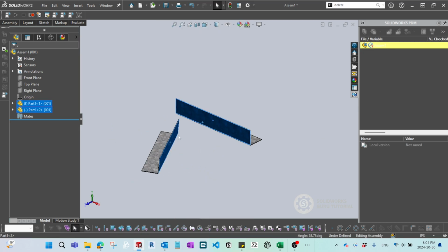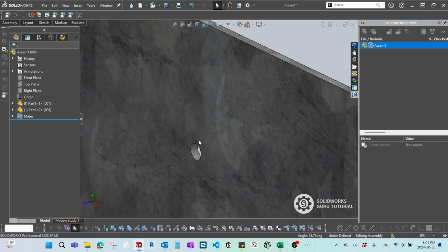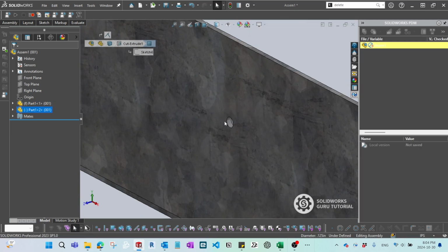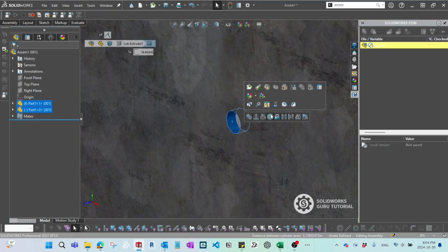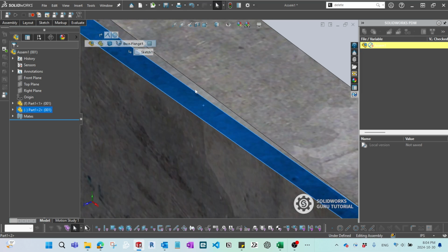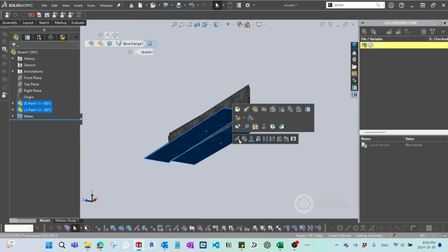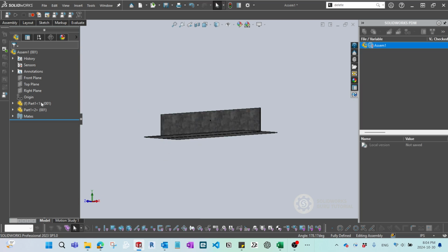We can press Control to activate the shortcut button. Then I'm going to click this one, and then this one, and make them concentric. And make sure this one is in line. So I'm going to assign the bottom face to the bottom face to be coincident together.